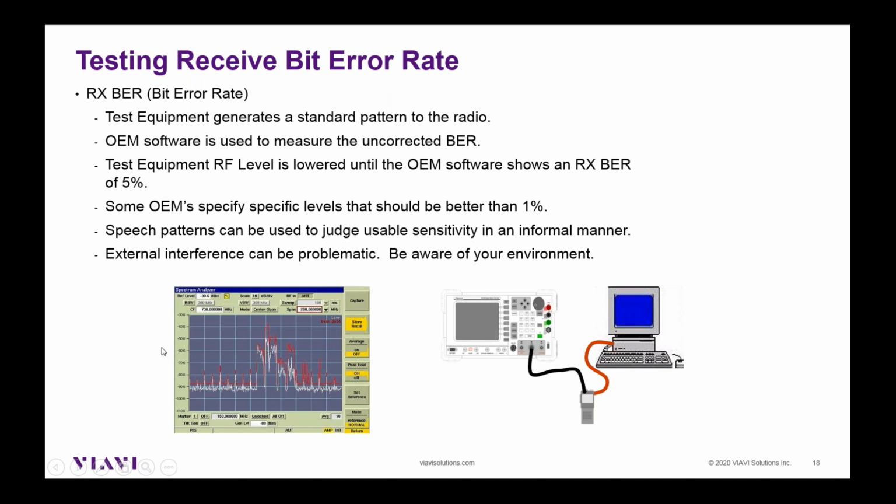So on the receiver side of that, we test the sensitivity of a receiver using those same types of patterns, a 1011, a 1031, and a service monitor will inject a signal that has one of those patterns. I'll say a 1011 as an example. And generally this is done at a low level, like minus 116 dBm or lower. And a computer would be connected to the receiver, and it would interrogate the receiver for what its received bit error rate was.